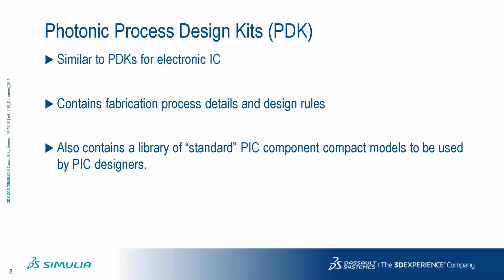So when you talk to a fab about creating your circuit, they would provide you with this PDK, which often also contains a library of standard elements that they design for you. And then when you put together your circuit, you can use those standard elements, or when you build your own element, you can use the information from the PDK to make sure that the circuit that you designed will work even after fabrication by that particular fab.